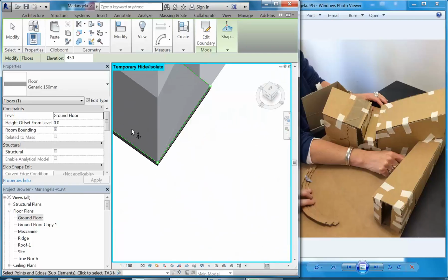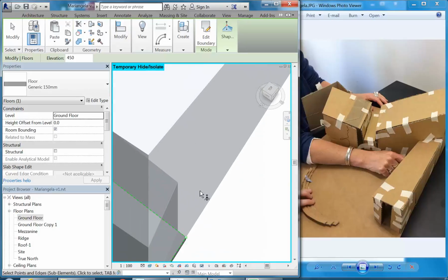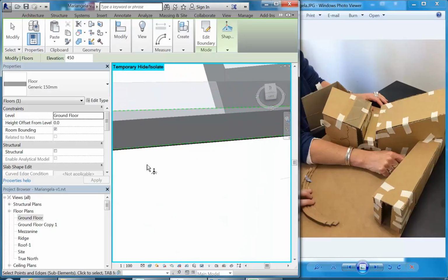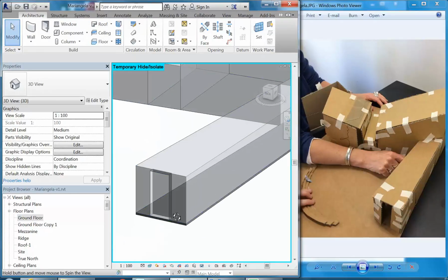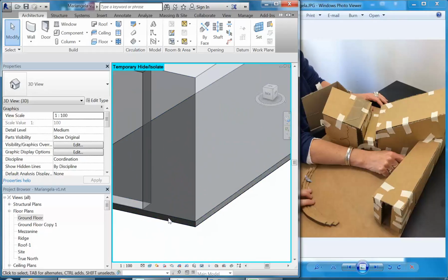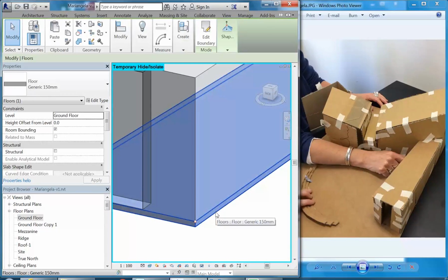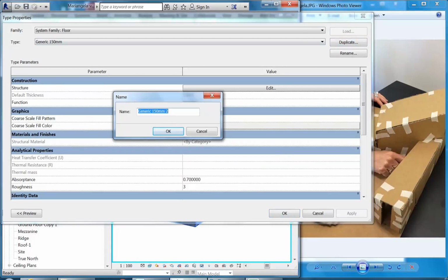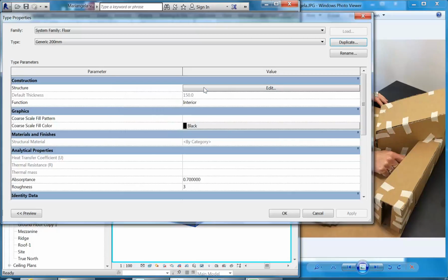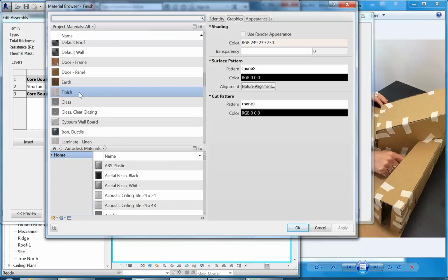It's sticking out actually in a way. Let's see what's happening there. Oh no, that's right, that's how it should be. Yep, that's perfect. Okay, so that's it. Now if I just cancel. Right, so just like the roof, I'm going to make that floor have a plane surface. So I'm going to just change the thickness to match the same as everything else, 200. And then after I've done that, change the material to that one I've used for everything else, finish.